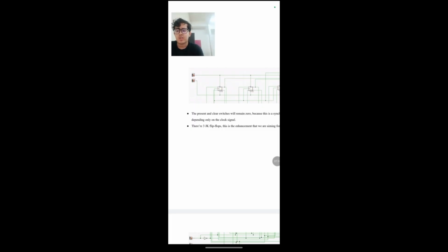Once in motion, our stop logic takes over the circuit, utilizing the matching network built with the XNOR and the NAND gate. The XNOR gate is constantly evaluating the elevator's real-time position, which is Q2, Q1, and Q0, against the passenger-selected floor.